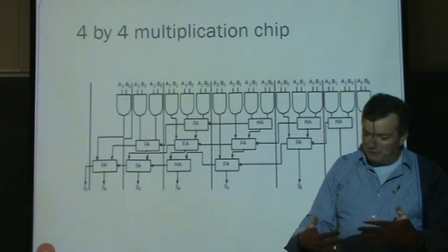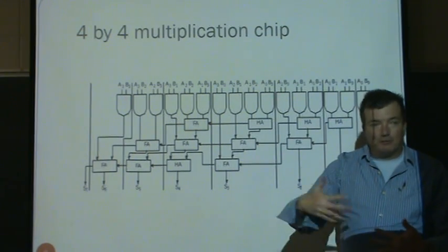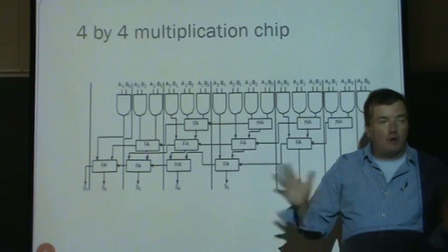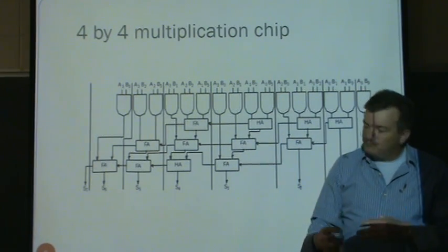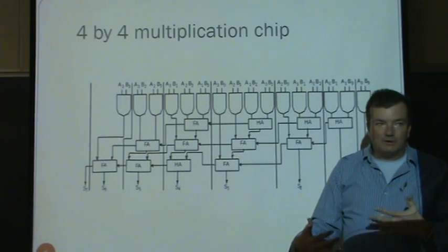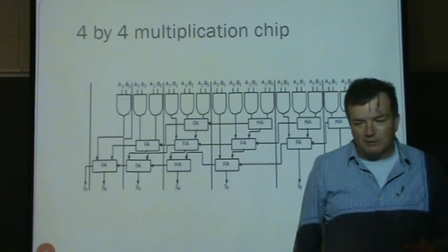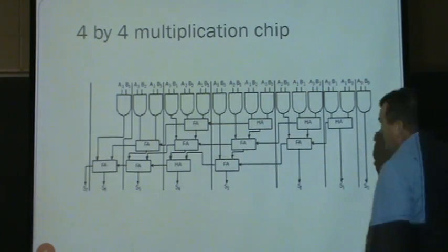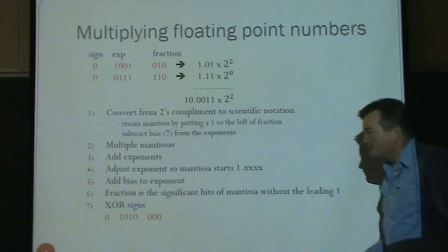So actually, if we have a 32-bit number times a 32-bit number and we multiply them, and the result is 33 or more bits, we're actually going to have an overflow error. We're going to say, sorry, the number's too big. So there's certain rules, like at least one of the numbers can only have 16 bits in it, otherwise we'll definitely have an overflow. So we'll take advantage of some of that too when we talk about it. We'll look at some of the appendixes on this talk.